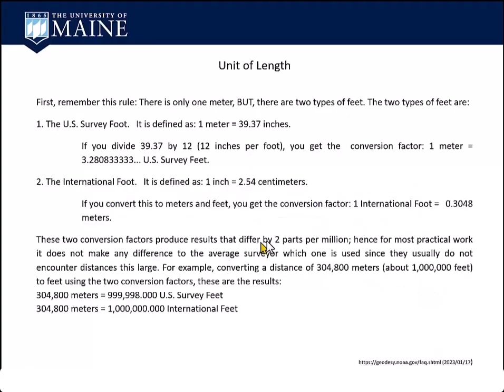I keep adding this to a lot of my presentations now, only because NGS is coming out with a new datum. It's going to do away with the US foot. But in the past, they established all their elevations in meters, and then they converted them to feet. But they used US feet for the conversion. I misspoke earlier. They only used US feet for conversion.